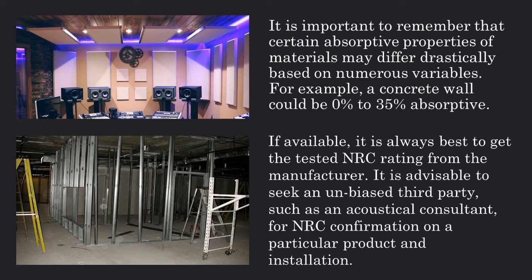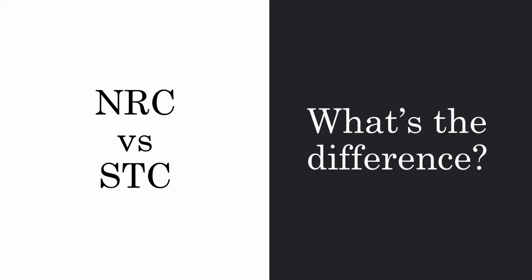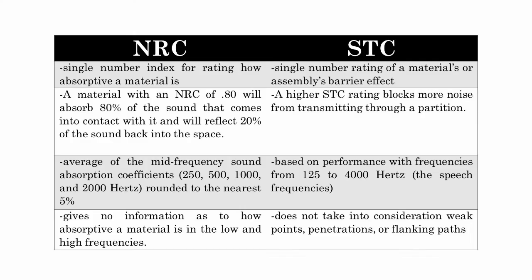It is advisable to seek an unbiased third party, such as an acoustical consultant, for NRC confirmation on a particular product and installation. So let us know the difference between NRC or noise reduction coefficient and STC or sound transmission class. NRC. NRC refers to a single number index for rating how absorptive a material is. A material with an NRC of 0.80 will absorb 80% of the sound that comes into contact with it and